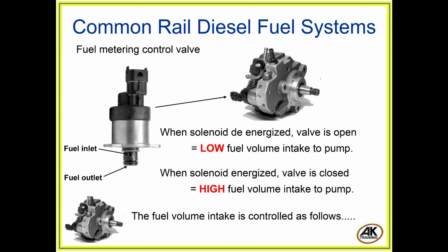Fuel metering control valve operation. When solenoid is de-energized, valve is open which causes low fuel volume intake to pump. When solenoid is energized, valve is closed which causes high fuel volume intake to pump.